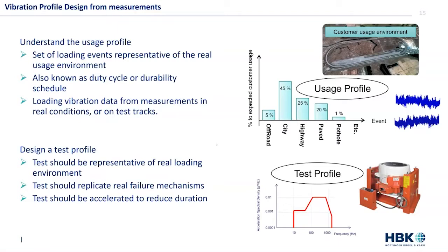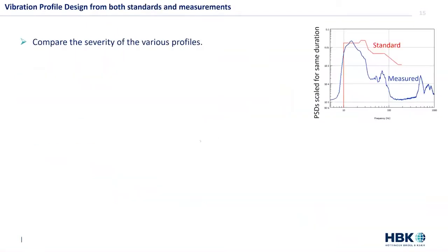So that's another route. Indeed, we mentioned the standards. Now we mentioned real measurements, but there is a third way, which is to design your vibration profile from both the standards and the measurements. So if you overlay, for instance, the PSD of your measured data with the PSD coming from the standard, and providing you scale them for same duration so that they're comparable, you might find that at some frequencies, maybe the measured data goes beyond the standard.